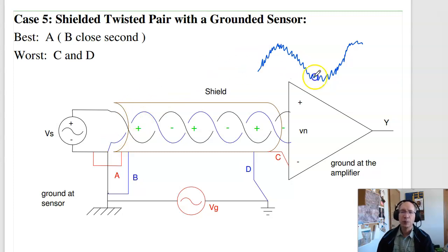The hope is that if the noise is everywhere and the signal is at low frequencies, I can build a low-pass filter which slightly distorts the signal but greatly diminishes the noise. That's a band-aid. Better is to not have noise in the first place. To get rid of the noise overall, typically use twisted pair shielded wire if you can afford it, or twisted pair if you can't afford it. And make sure there's only a single ground. You don't want ground loops.